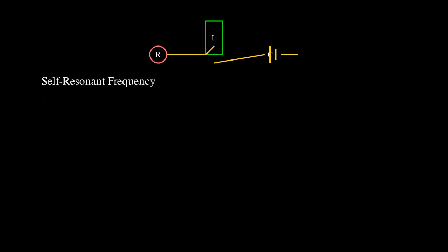Every resistor has a self-resonant frequency where the inductive and capacitive reactances cancel out. Below this frequency, the component looks mostly resistive. Above this frequency, the component may look more like an inductor or capacitor, depending on which parasitic dominates. To minimize these effects, RF resistors are designed differently from regular resistors. Carbon composition resistors have relatively low parasitic inductance but can be noisy. Metal film resistors offer better noise performance and stability. For the highest frequencies, chip resistors in surface mount packages minimize lead inductance.